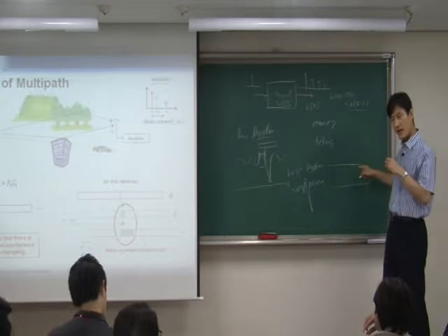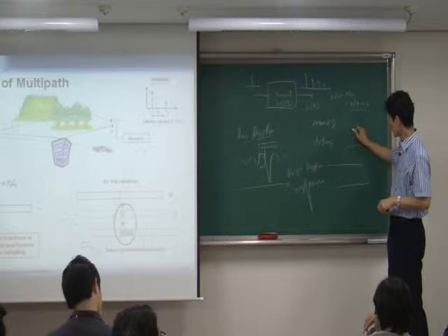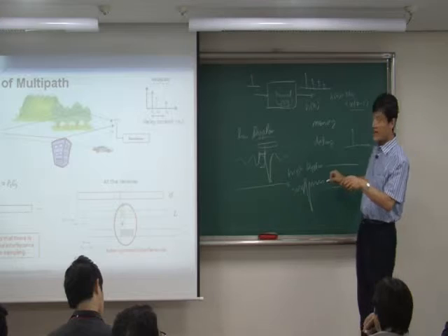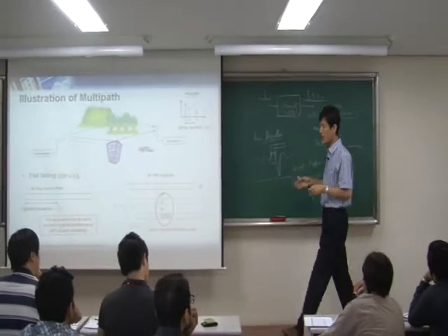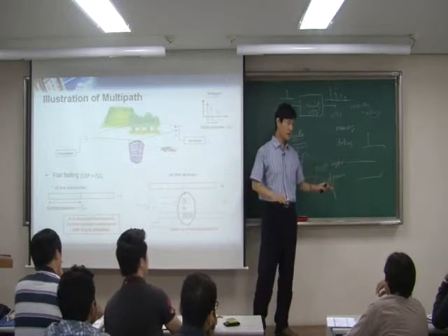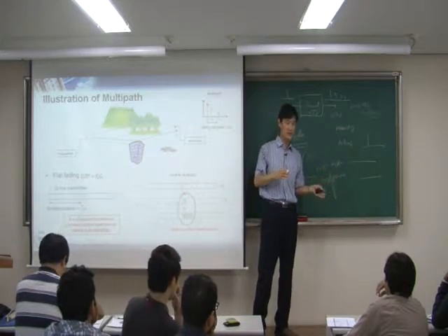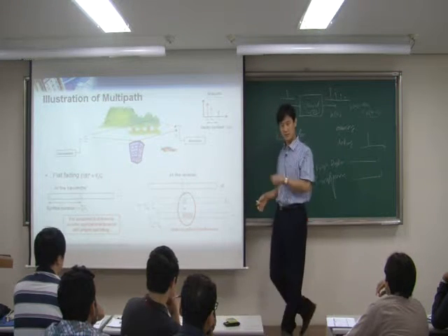But in order to make it flat in the frequency domain, your time domain should have an impulse, right? This one is not an impulse, but I can consider it as an impulse. No problem, because anyway, I recover perfectly. So I would consider that as flat. It's almost flat, right? From my point of view, it's flat anyway. It's a flat fading.